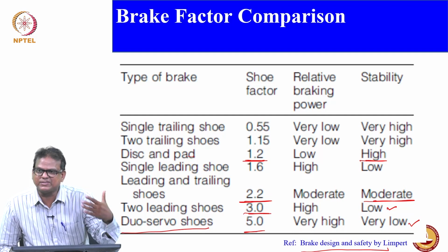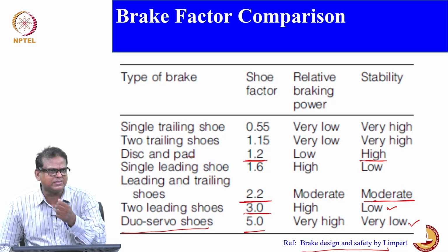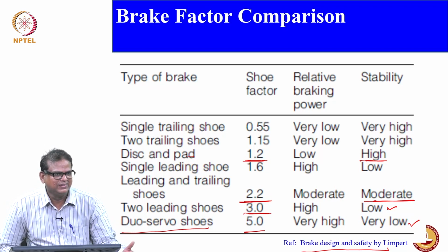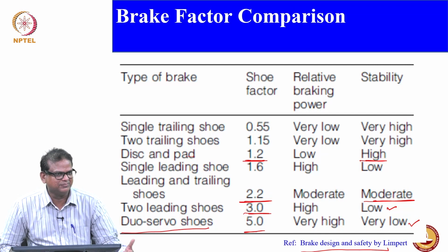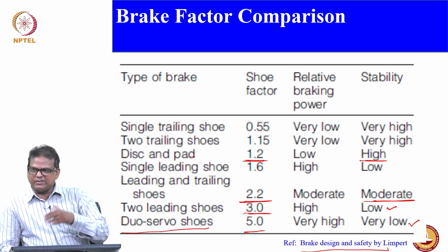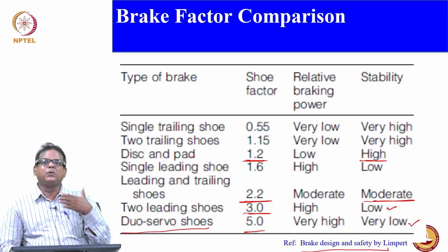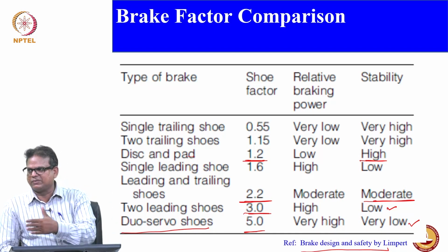You always look for stability, that is very critical, because it is a reliability component. The brake system is a matter of life and death, a catastrophic thing, right. So that has to be taken care of while designing. So you can always replace a drum brake with a disc brake. If you do vice versa, that is going to affect the stability and lead to catastrophic failure.